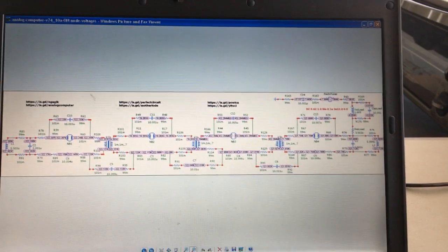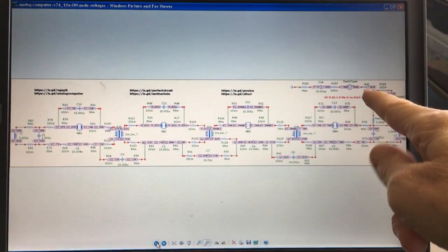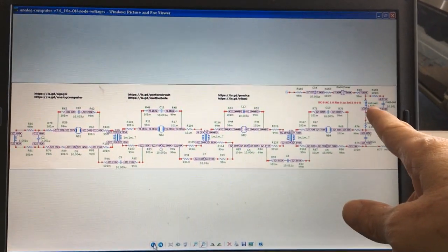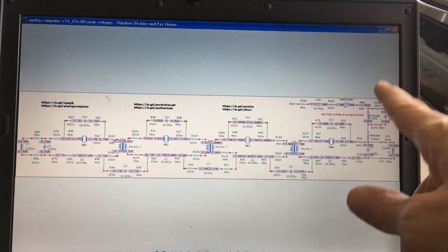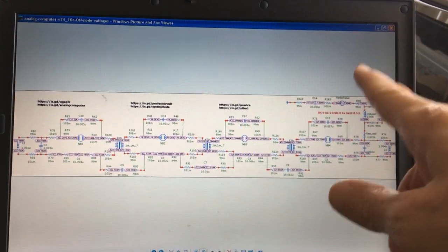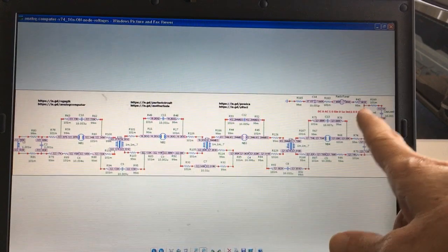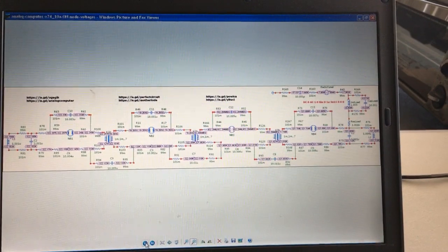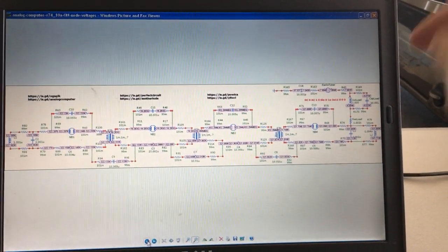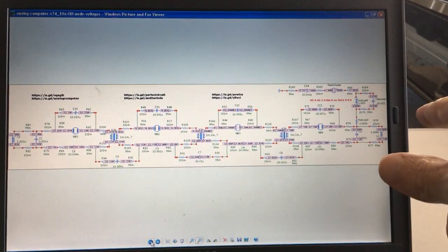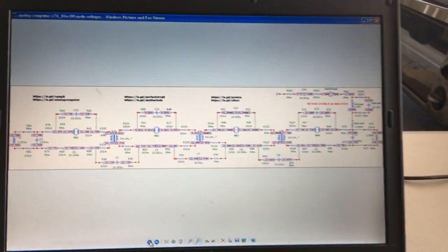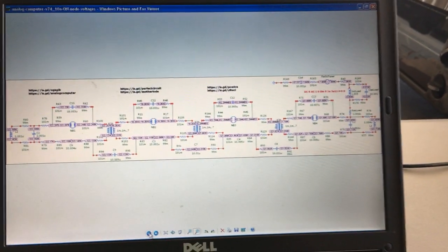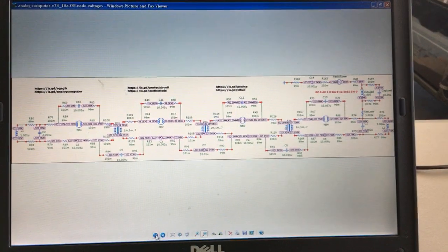The other requirement is that the voltage input is really a stimulus. It's not an energy source. So we're not getting energy from the air or whatever. It's just a stimulating sine wave of a very high frequency. It has to be in the range of about a microvolt minimum and 10 volts maximum, more or less, give or take. I'm just extrapolating to whole powers of 10. Anything greater than that or less than that doesn't work. So these are windows of opportunity, parameters of minimums and maximums you have to stay within. And within those parameters, you get a lot of wiggle room. You can do whatever you like.